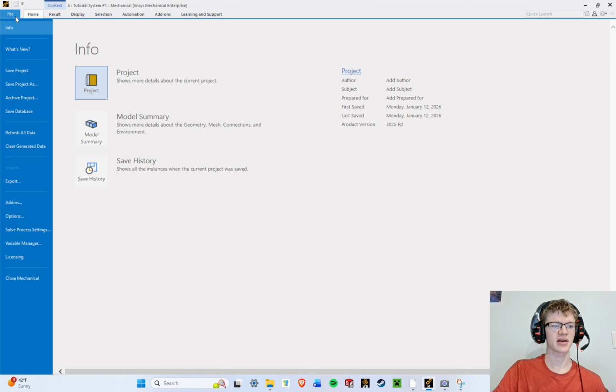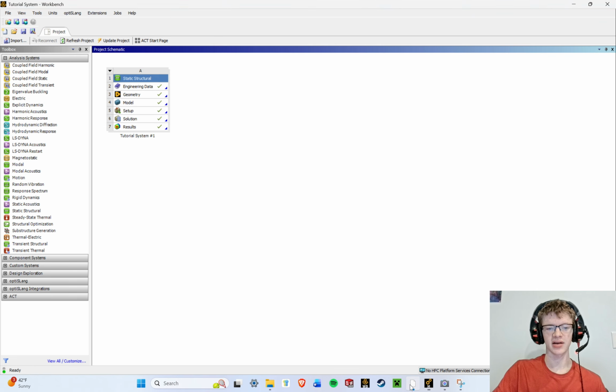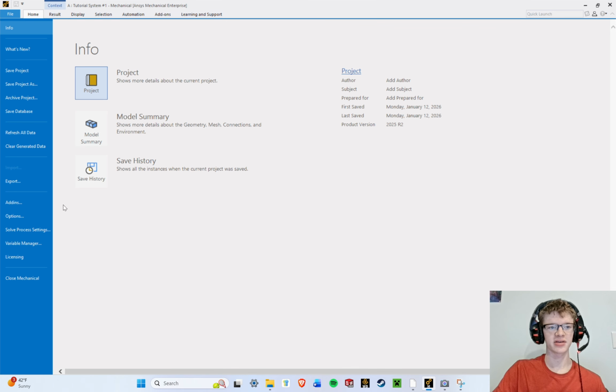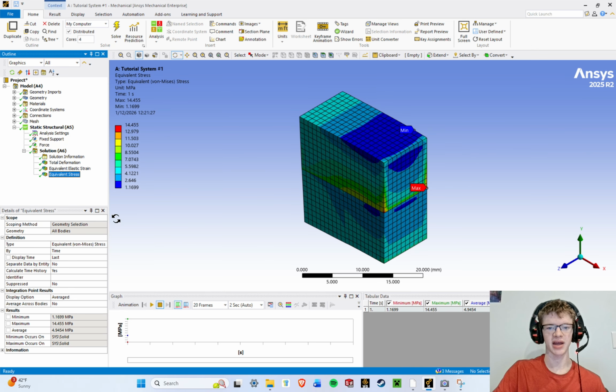So you can click this icon, or this icon, or this icon, and that's going to save your results for you in case something happens, because sometimes these models can take hours to solve, and we don't want to lose everything now that it's finally solved. It's just good practice to save after it's done, as well as in case you decide you need a finer mesh. Instead of solving again and losing the coarse results you had, you save that, so you at least have some results, and if something fails, you can try again and still have a backup to go back to.